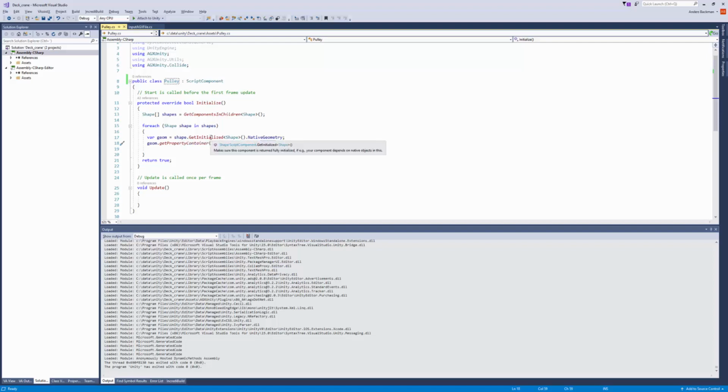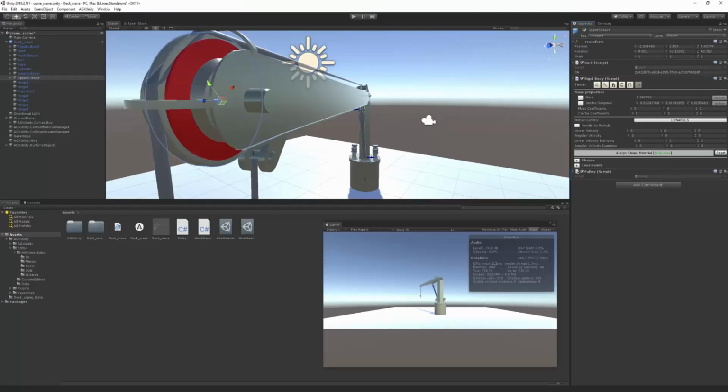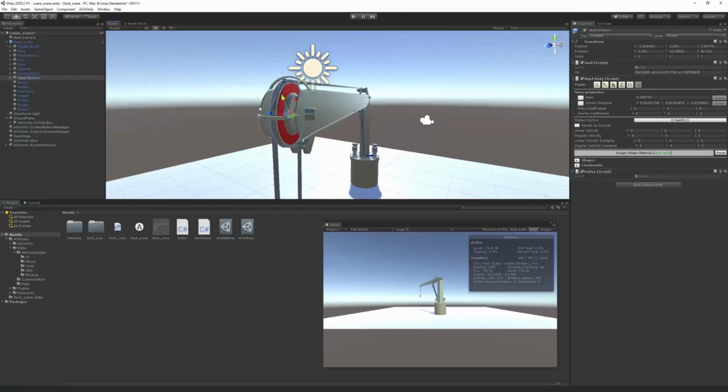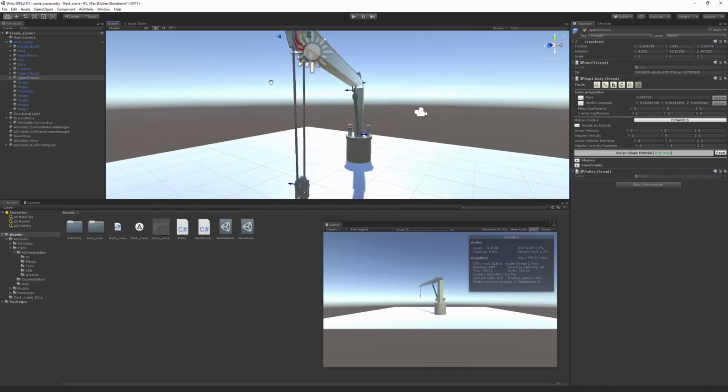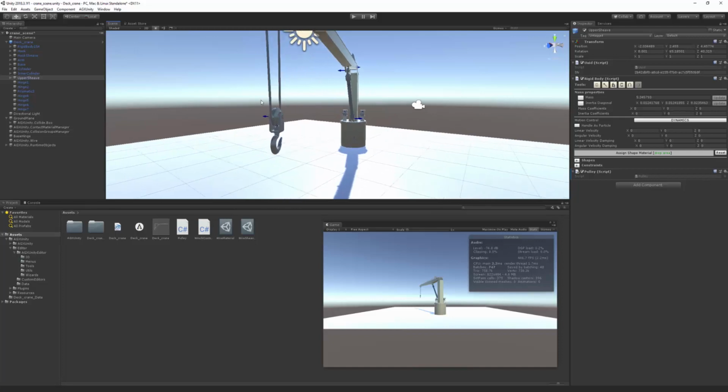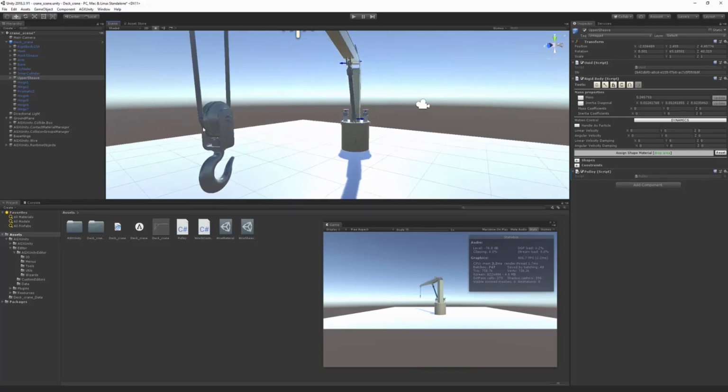And when the wire collider algorithm sees that property, it will always try to move the contact nodes of the wire to the center line of the baseline of this cylinder, so that it will be much more stable and it will be harder to move the wire sideways, which is perfect for this implementation of a sheave.